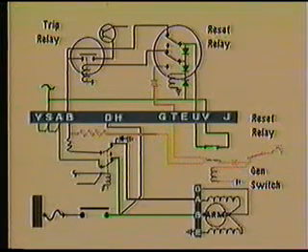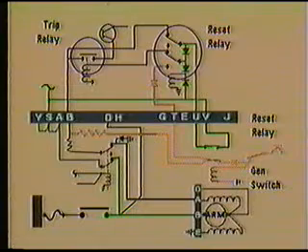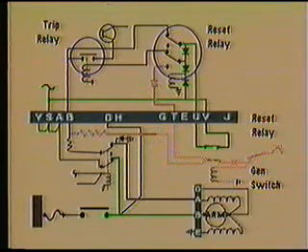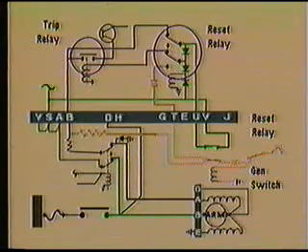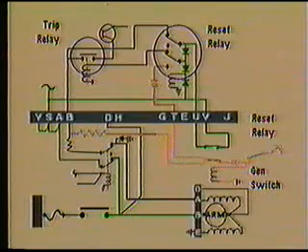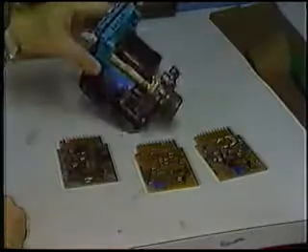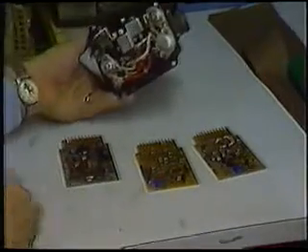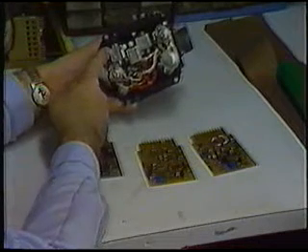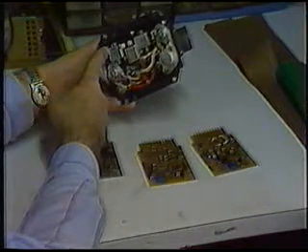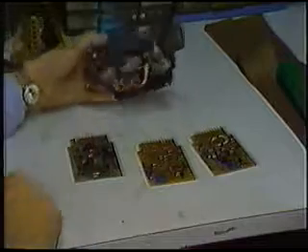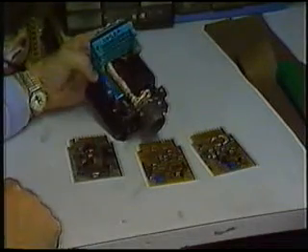The second relay, which is referred to as the reset relay, is of conventional operation. It is spring-loaded to the normal position and energizes to move to the reset position when electrical power is supplied. The control panel reset relay, which is installed within the control panel itself, should not be confused with the system reset relay, which is installed in the airframe wiring.